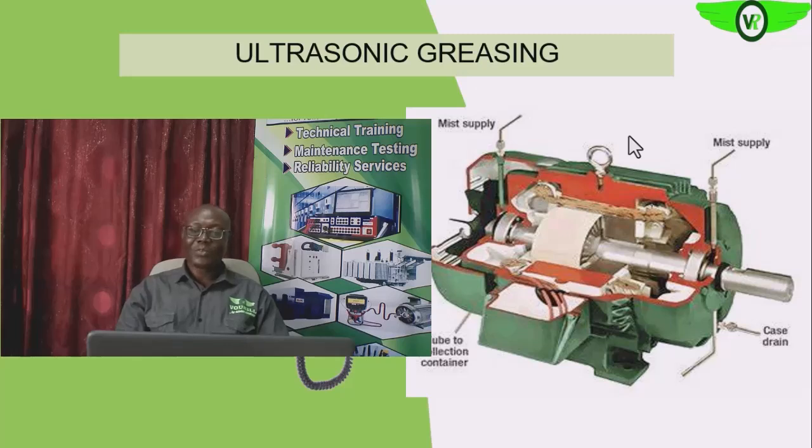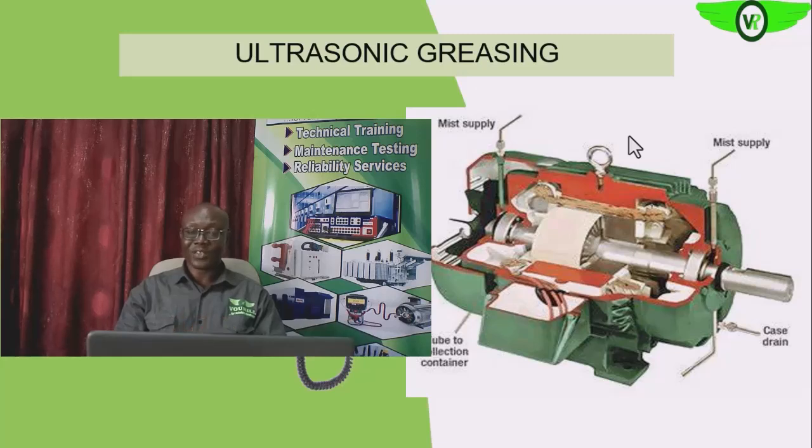So how do we know when to actually stop greasing? Though experience may tell us, that experience can also fail us. If we use ultrasonic greasing, as we are listening to it or viewing the ultrasonic signals directly, we will see the right point when the grease on it is enough. That is when the vibration or the ultrasound has reduced. So that will now introduce us to ultrasonic greasing.